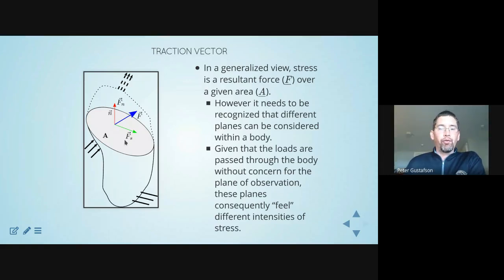Now the resultant force over this entire area is the sum of all the stresses times their differential areas. So really those are differential forces. Those differential forces are all vectors. You sum them up by multiplying them by their area. And what you get is a resultant force, here shown by the vector F, which I will circle here. It's obviously a blue vector. So that now is an internal resultant force over an area that was exposed by this imaginary cut.